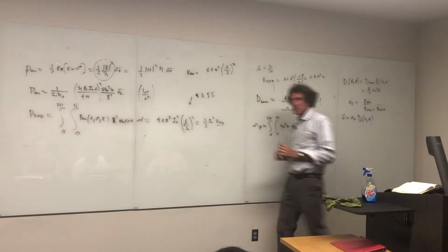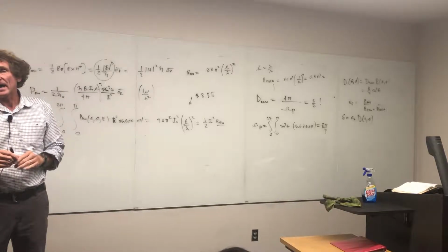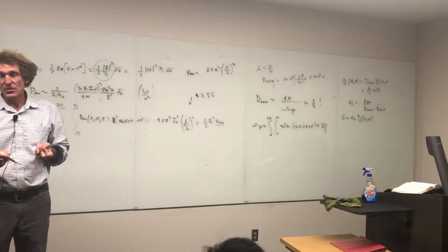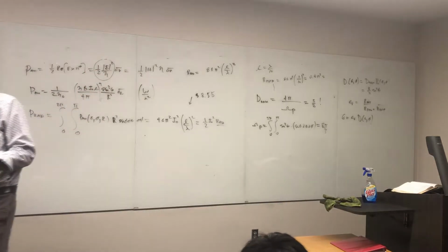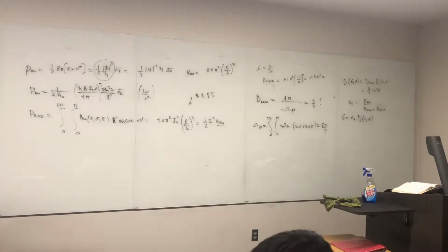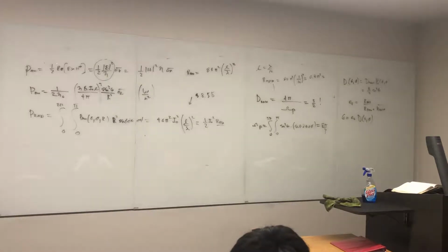Now, I didn't give you a specific frequency in this, but for any given frequency, if you know the actual length of the antenna, you can get length divided by lambda. Follow me? Now you have that, square it, multiply by 80 pi squared, and you have the radiation resistance. To get the AC resistance, you would approximate this. You would take the length of the antenna, then divide it by sigma of copper, probably, times the area the current flows through, and that would be simply 2 pi times skin depth times radius of the wire. I'm making sure I'm talking through the entirety of the problem. Got me on that?